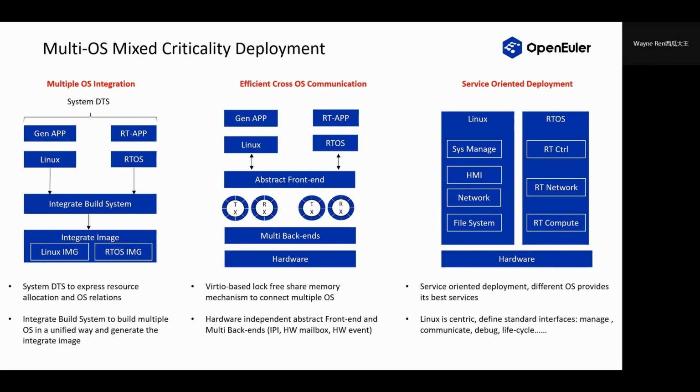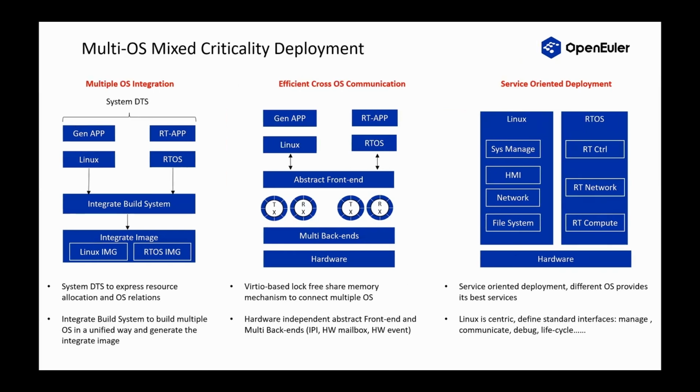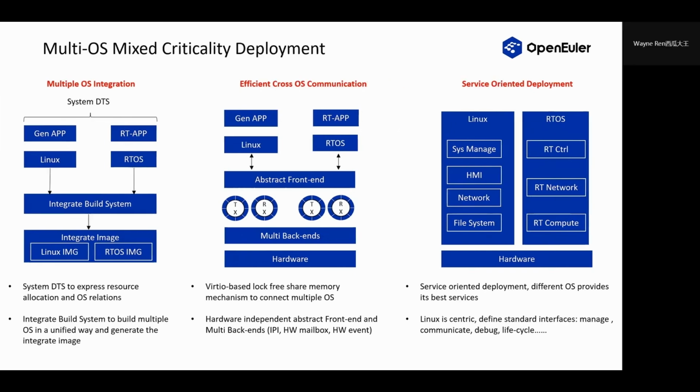Number 3, service-oriented deployment. On the basis of efficient cross-OS communication, we want to implement service-oriented deployment, where different OS provide their best-fit services. For example, Linux provides system management, general network, and general file system. An RTOS like Zephyr provides real-time control, real-time network, and real-time compute. In our approach, Linux is the center, and defines standard interfaces for management, communication, debug, lifecycle, etc.